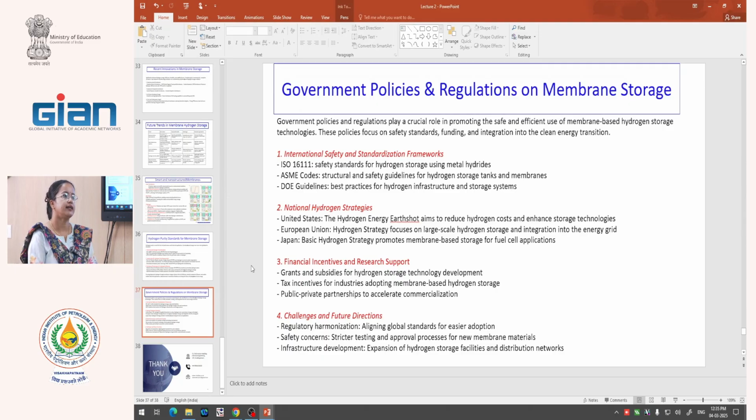Basically, the guideline is to check your permeability after every cycle. If you are working in the membrane field, then you must know that after each and every cycle there is a washing protocol or a regeneration protocol. After this regeneration and washing protocol, we generally check the permeability of the membrane. It is often not possible to regain the initial permeability.